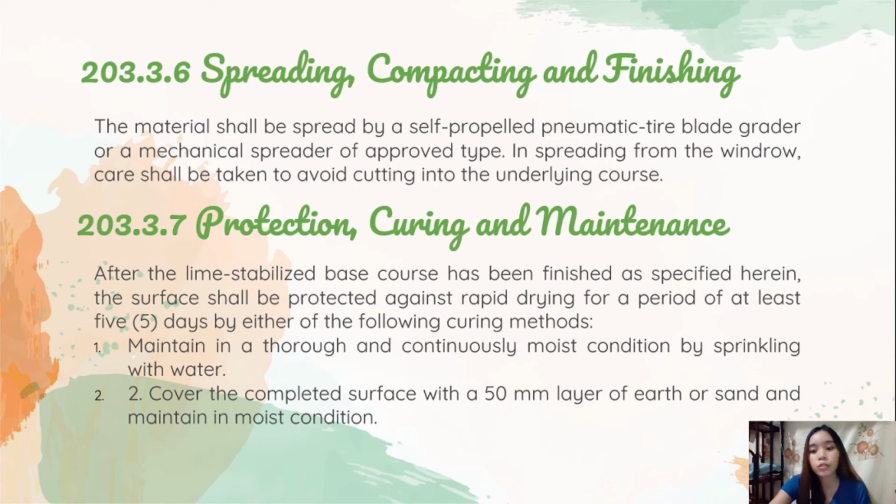Then rolling shall continue until uniform texture and satisfactory compaction is obtained.